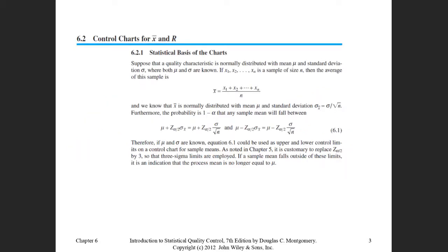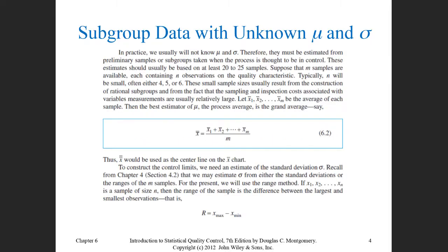The first type of the variable control charts is the X bar R. This is the most commonly used. In this chart, we use the X bar referring to the average of the data measures, and the R referring to the range. The range is calculated based on the subtraction of the maximum and the minimum. We will see more about the formula here.